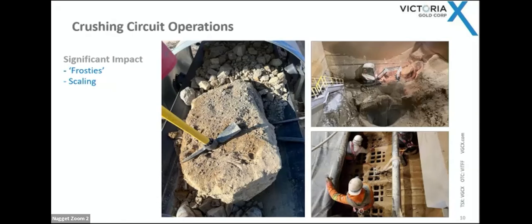And then here's a screen panel on the secondary feed. Those are 4-inch openings that are completely blinded off by fines. So the takeaway on this one is this material will freeze up. You need to have heat in spots to keep this from going. And then just think about the maintenance time, okay? Having to deal with these types of problems can extend maintenance time up to 200% of just the simple tool time, just by virtue of how much material has to be scaled.